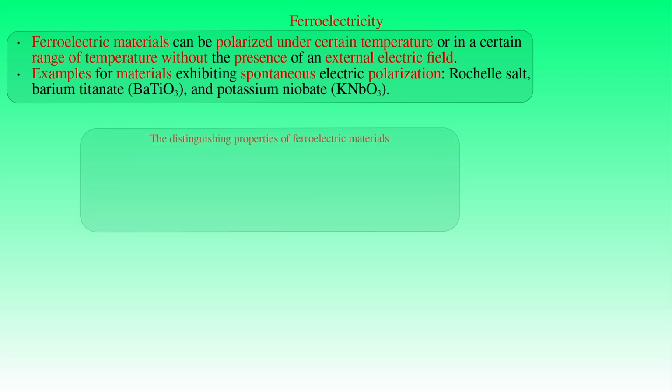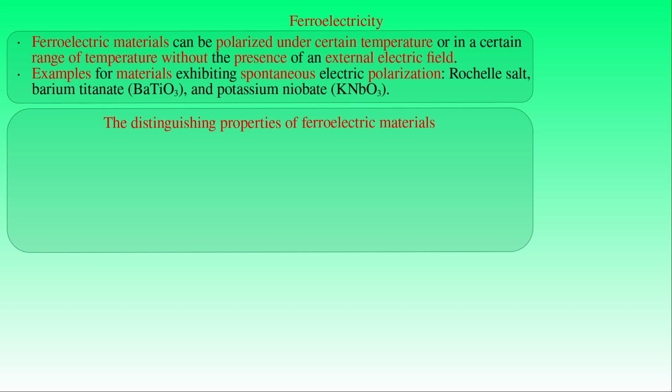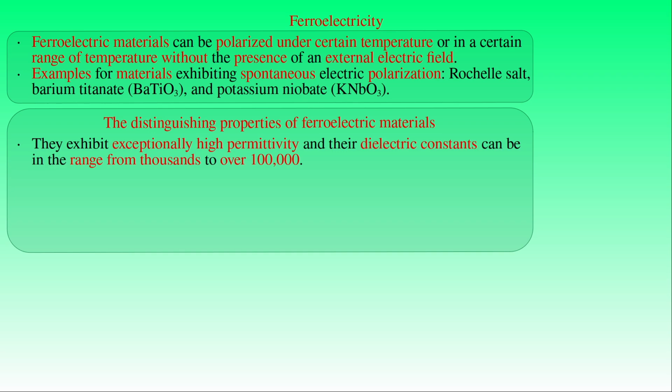The distinguishing properties of ferroelectric materials can be summarized as follows. Ferroelectric materials exhibit exceptionally high permittivity and their dielectric constants can be in the range from thousands to over 100,000, whereas the values of relative permittivity are typically below 10 for common dielectrics.